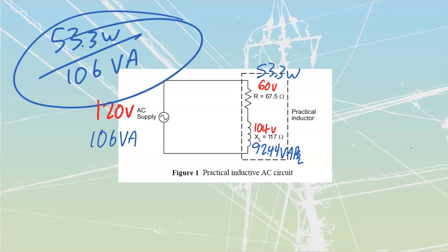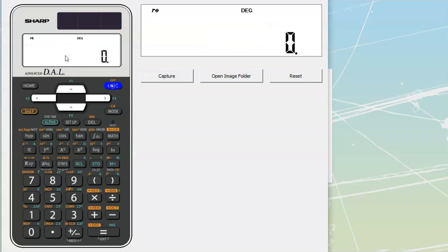Another thing that we can do with that power factor is find it by taking the cosine of our angle. What is cosine? Cosine is simply our adjacent over our hypotenuse, right? That is what the cosine is. Adjacent is our watts. Hypotenuse is our VA. The exact same thing. So if I know my circuit angle, which we calculated before was a 60-degree circuit, I can just take cos 60, which would give me 0.5 for this one as well.